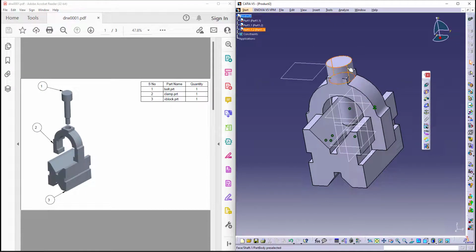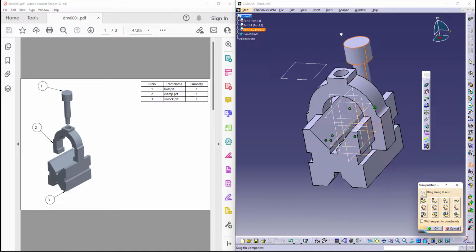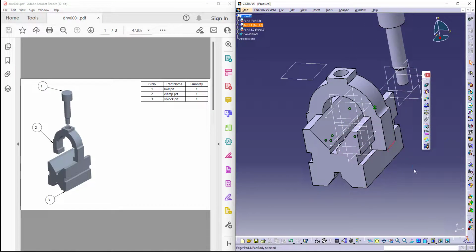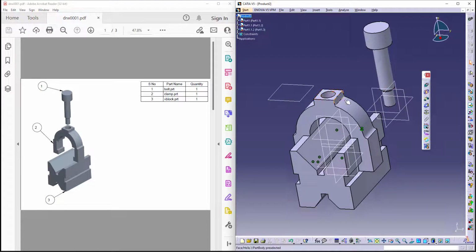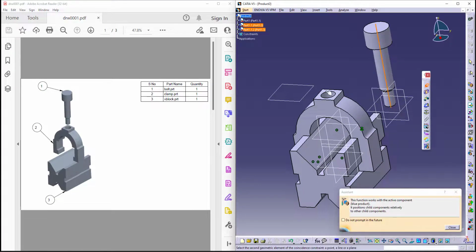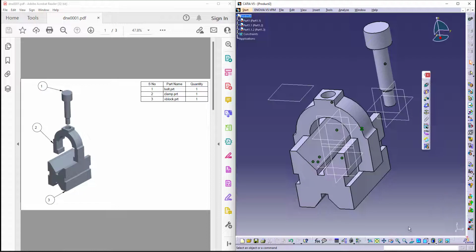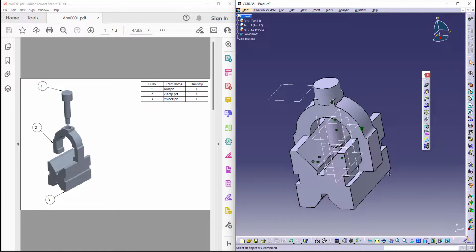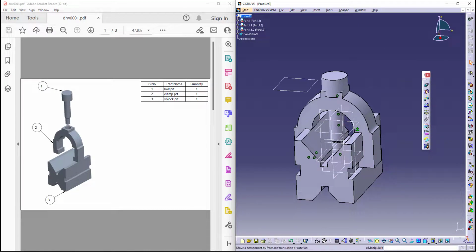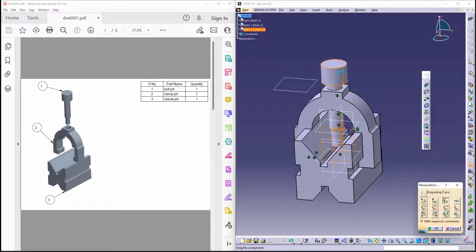Now, once it's over here, let me try to move this. Now again start constraining. This should be in line with this face. So let me try to coincide the axis as well as the axis. When I click on Control U, it auto updates and goes there. Now when I'm trying to give the movement, I'll try to give the movement with respect to the axis. So I can only move it via Z axis.